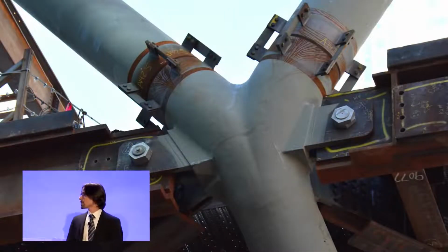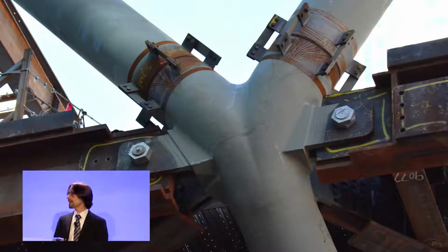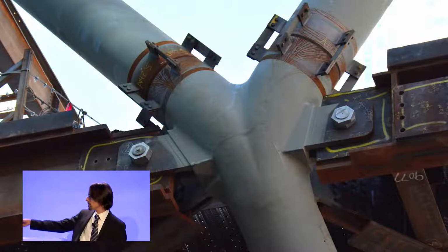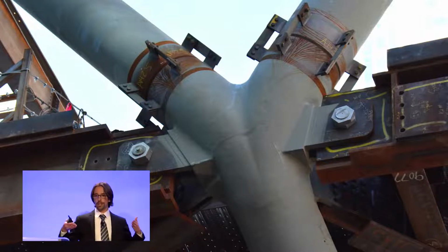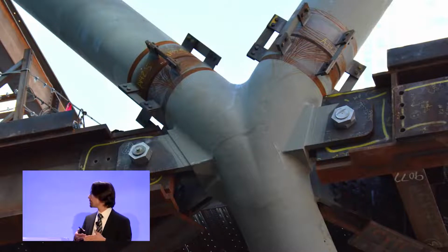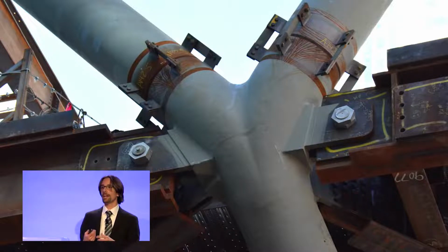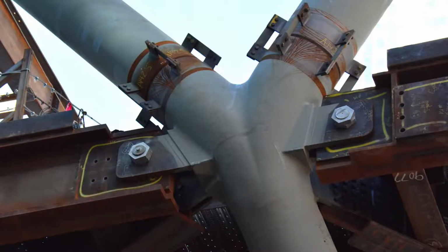This particular junction point, which is what we call the Bostec level cast node, has actually 7 structural elements all framing together. You have a tubular section coming in from the bottom, 2 drag struts coming in from the side and 2 from the rear, and then two tubular elements coming from above. Again, all very heavily loaded, but with castings, we can make that transition look graceful.